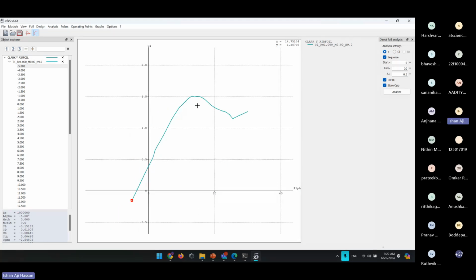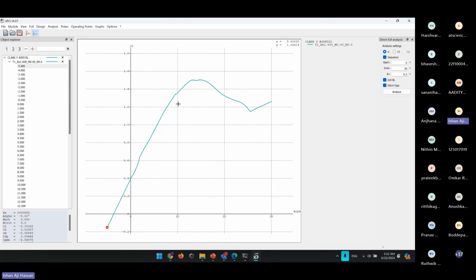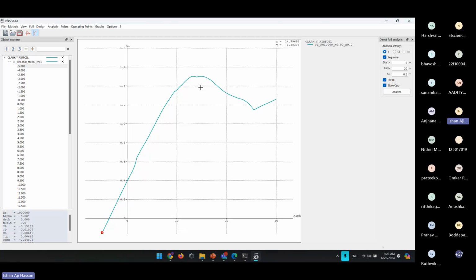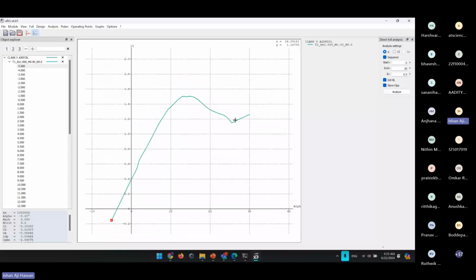The stall is happening because at some point, the airflow gets detached from the airfoil. In stable operating conditions, your airflow will be staying stuck to your airfoil. But at stall, the flow separates off and forms some turbulent vortices. At that point, you'll start to lose lift, because the way the airfoil generates lift is essentially by changing the direction of the air entirely. If you've got some air coming in along the x-axis direction, ultimately when it leaves the airfoil, it'll be getting some downward velocity component as well.